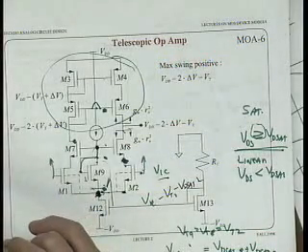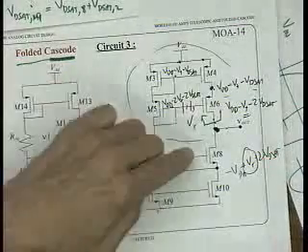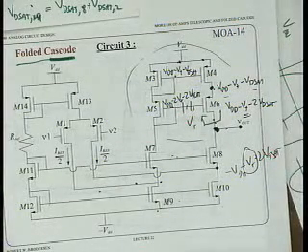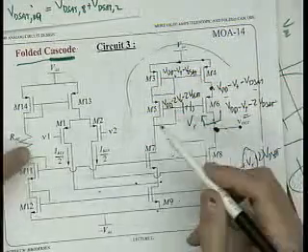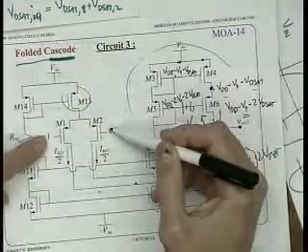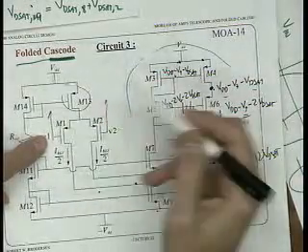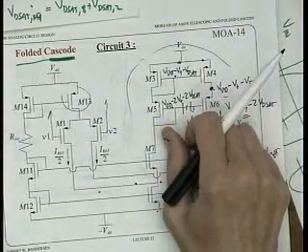The question is, in this circuit, we actually just fold the input to the other side, right? Right. So when we come to the common mode, when we increase the input, we should also increase the VDS of M13. M13, okay, right here. Yeah, we also increase the VDS. So how come the voltage at the source of M7 and M9 doesn't change?